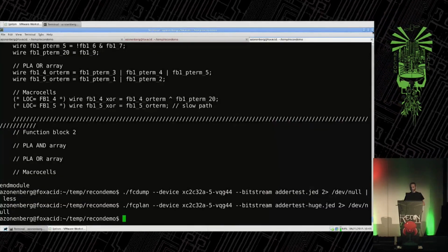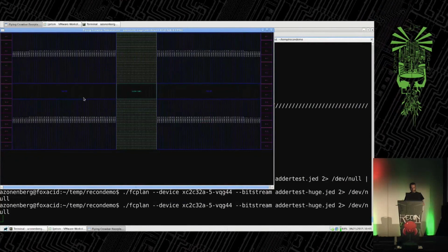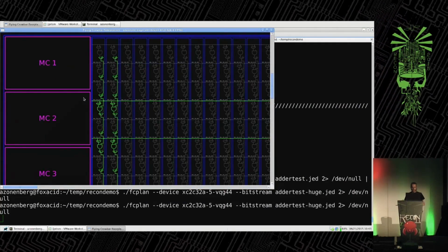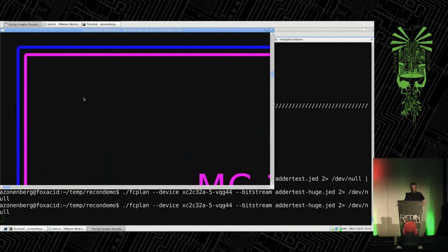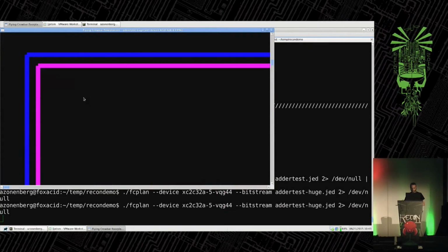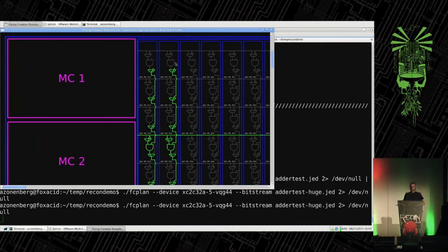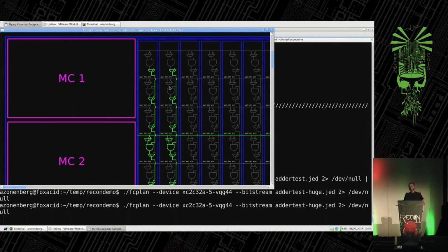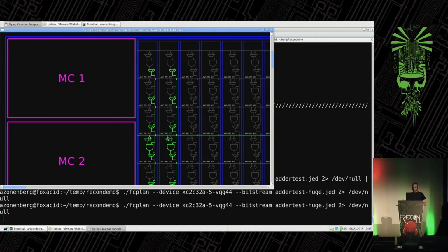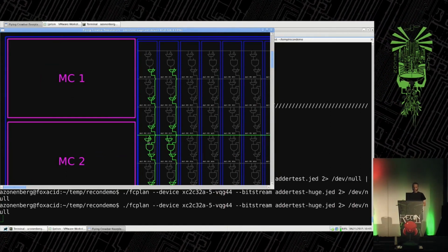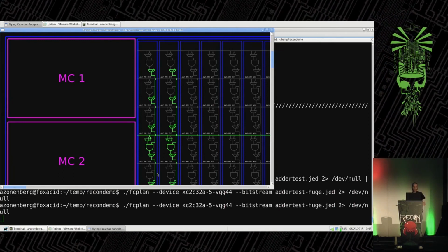Guess I found a bug. The scroll on this thing is really sensitive. All right, can I go just one click in? All right, that's probably good enough. So you can see what we've got. Initially, we're bypassing all the inputs, so we're not using the first couple rows coming off the global routing. Then down here, I've got one signal coming in. It's hooked up over here to X. It's hooked over here to X prime, goes into the AND gate. Then we go down there and so on. So we do actually have a full physical layout viewer at this point.